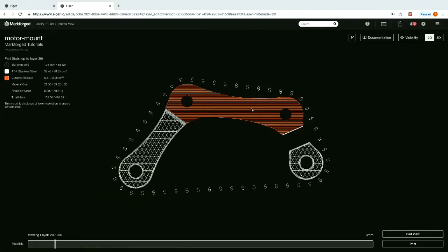Yeah, that's the ceramic release material that Daniel was just mentioning. This is how you remove the part from the raft. Once the part gets printed, it gets washed, and then after it is sintered, that ceramic material basically gets incinerated away, and then you can just break the part off of that raft a lot easier. It's tacked down to it so that it prevents warping while in the sintering oven, and then that ceramic basically magically disappears in the furnace, and then you can break the part off afterwards.